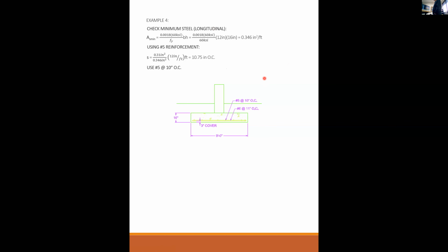So that's why I'm saying 3.5 is a good average, and it actually covers you up to a number 9 bar. If you had a 10 or 11 bar, you might actually want to revise it because you're a little unconservative at that point. But up to a number 9 bar, maybe even sneak it to a number 10 bar, 3.5 is acceptable for determining your rough dimensions. And then you could always go back and refine it later if you needed more accuracy.